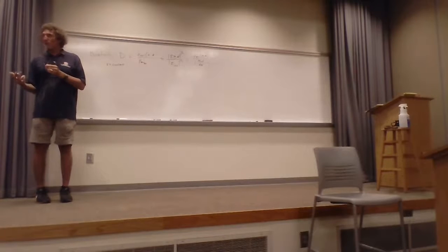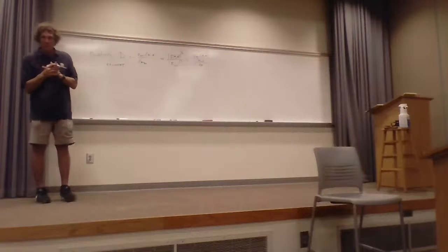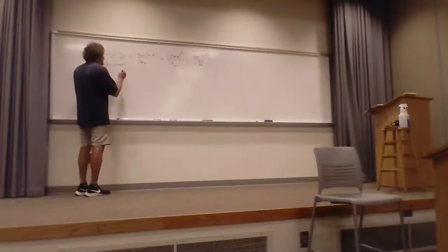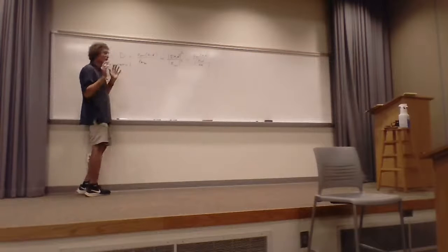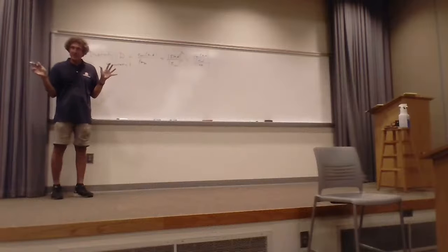You'll notice there's no R in that one. Normally it would be P_rad over 4 pi R squared. But we're putting R equal to a constant, and it's better to say R equals 1 meter, theoretically. Don't worry about that. It'll always cancel the R's.